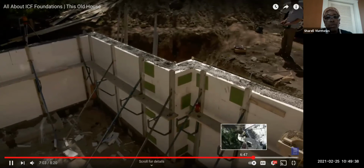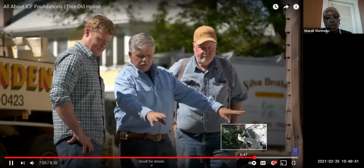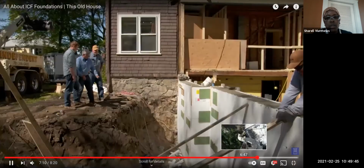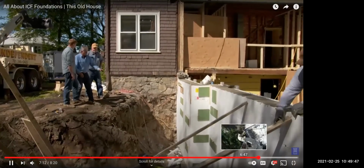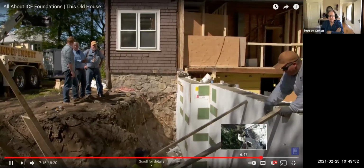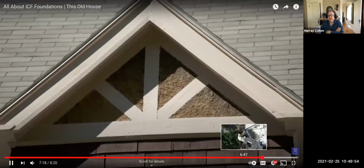Once the foundation is poured, the next step will be to remove all the wood and all the debris down below. Then they'll waterproof the foundation from the grade down. They'll put a primer on it, and that primer will accept a stucco. Stucco will match what's up on the rest of the house.